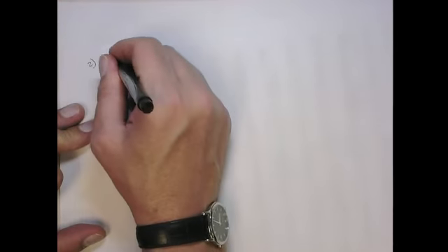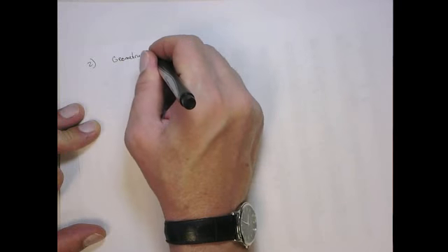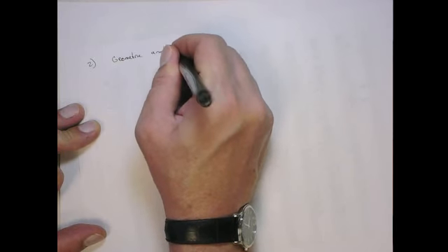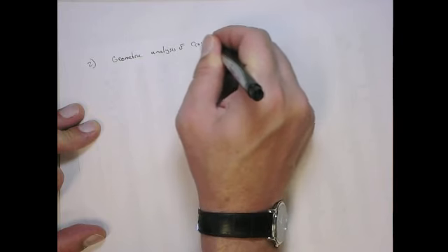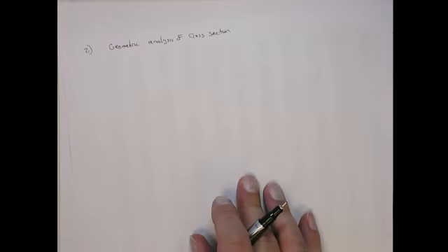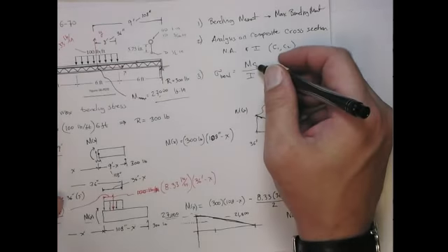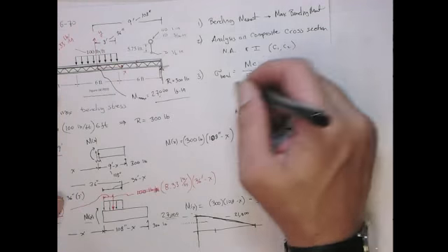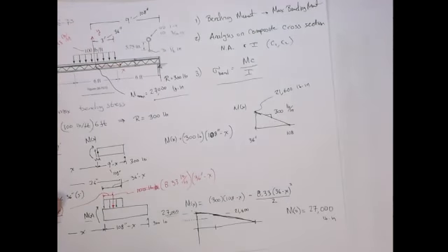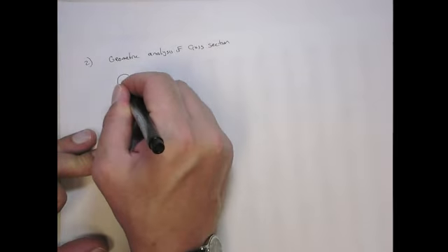So we need to get the second step. Now we have to do the geometric analysis. Okay, so we need to know the location of the neutral axis and I. We need to know to get the right c and I to apply the flexure formula. That's actually the easiest part, the Mc over I calculation, right? Okay, so let's make a little bigger picture.